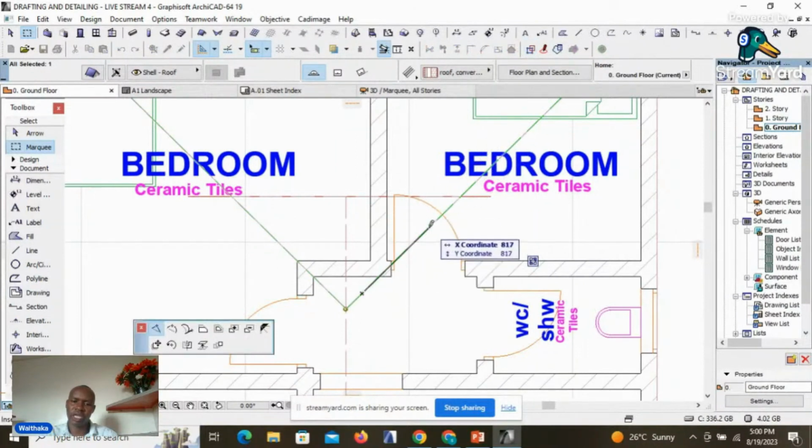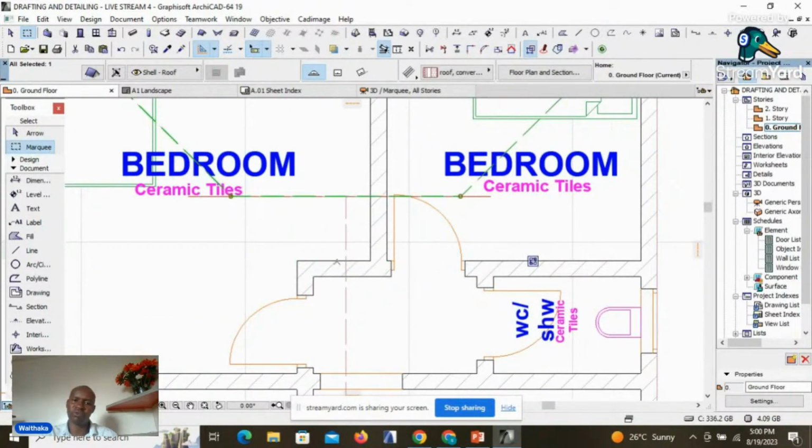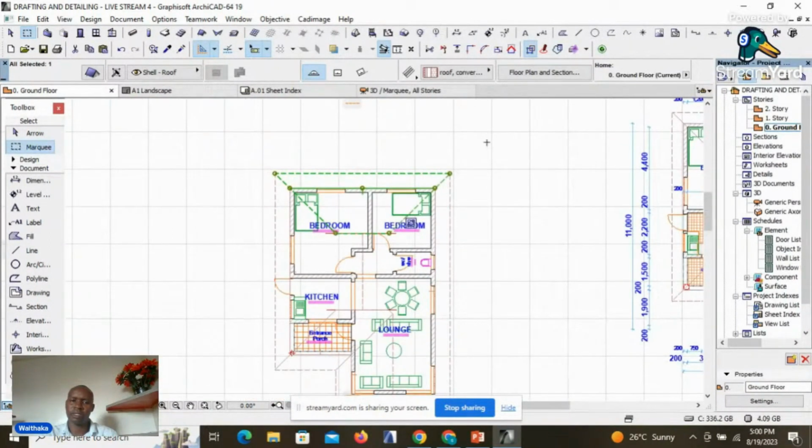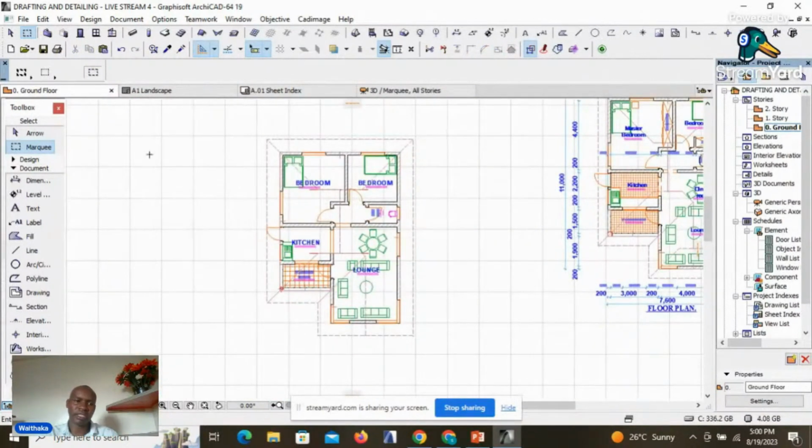So we click on the edge of this roof part, then pick deduct, and then we will step over this triangle that we want to deduct from this roof. And there we are, we've deducted that part.